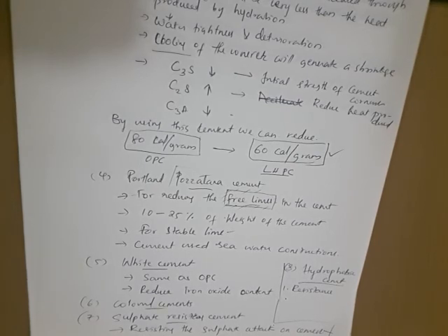This is made by adding water repellents during cement production, and these water repellents make a water resistant monomolecular coating around the cement particles, and it will resist the effect of water content and resist hydration. Before using it for concrete, by abrasion this molecular coating will be removed, and by adding water the hydration takes place.